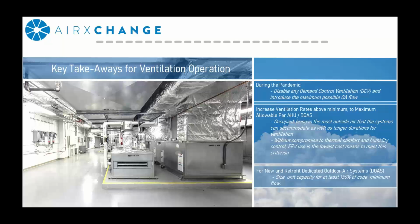And if the building is considering replacing or designing a new ventilation unit, size the unit for 150% of the code mandated flow for periods of urgency. This is going to help you future-proof your building or your space in anticipation that anything like this would ever happen again.